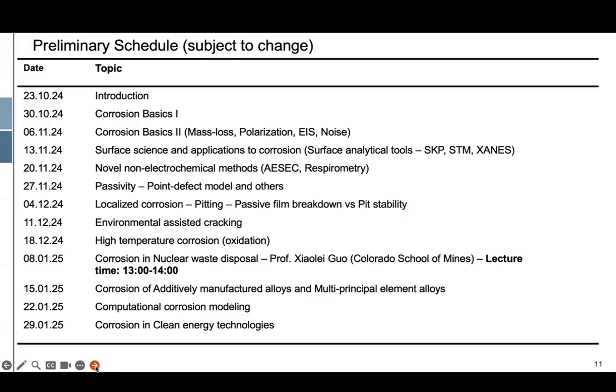We will introduce you to the electrochemical interface, the interface structure, and then the equations that describe the equilibrium between the electrolyte and the metal, the Nernst equation, and then the concept of the Pourbaix diagram and how we can predict whether corrosion is going to happen at a given condition or not. And then we will move on to corrosion kinetics, because thermodynamics and kinetics are two sides of the same coin. So we need to understand both of them together to understand this entire process. We'll discuss the Butler-Volmer equation that will plot the Evans diagram and the mixed potential theory that will set you up for the future chapters.